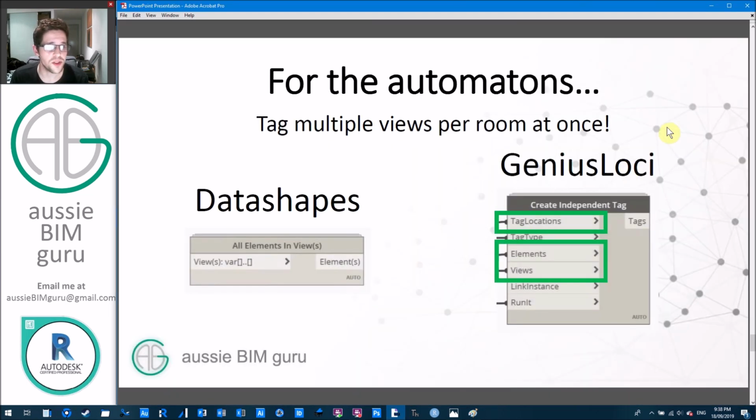For the true automators out there that really want to make these scripts very powerful, consider looking into ways to make the tags work for multiple views per room at once. So find a way to isolate all the elevations that belong to a room, for example, such as finding all the elevation markers inside a room and visiting them all using the script. Obviously much faster, and you could tag an entire room layout sheet in one script if you did it right. I won't build it for this one because it's quite specific, but keep in mind that Data Shapes, a custom package, has a node which will help you called All Elements in Views.